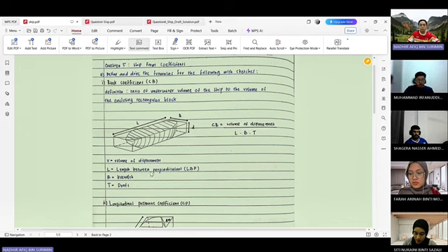Okay, the final KG is 45000 plus 2581 divided by 9000 plus 70750 minus 160. The answer is 4.962 meters.